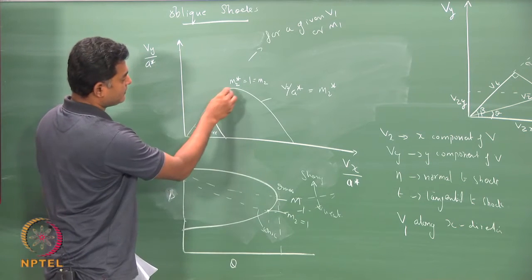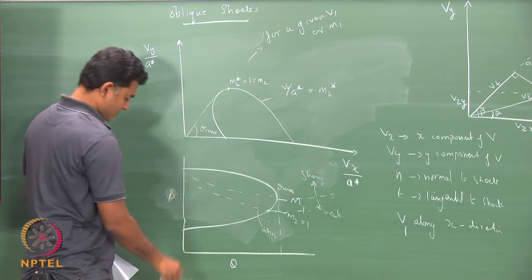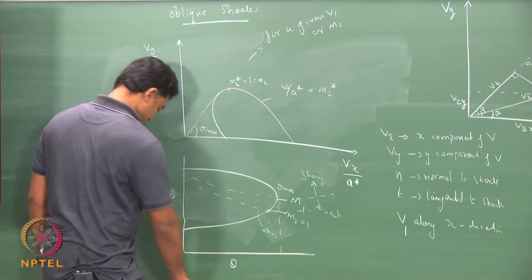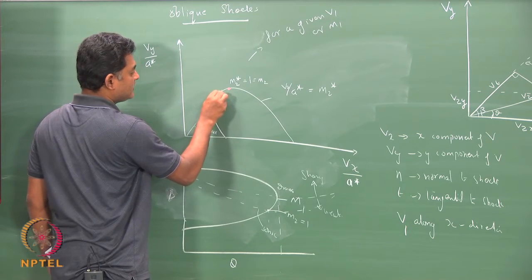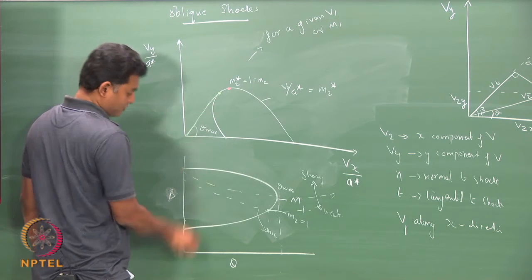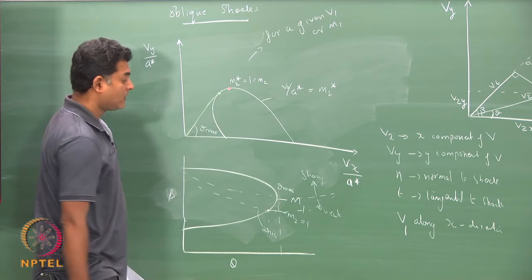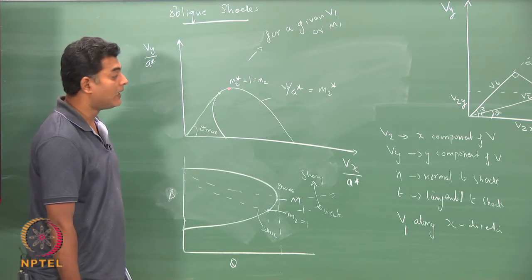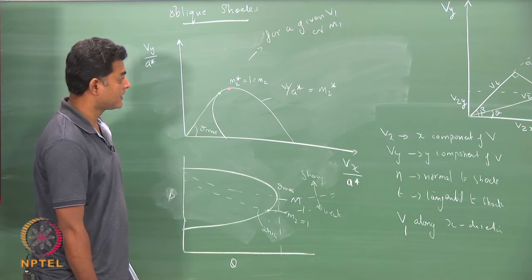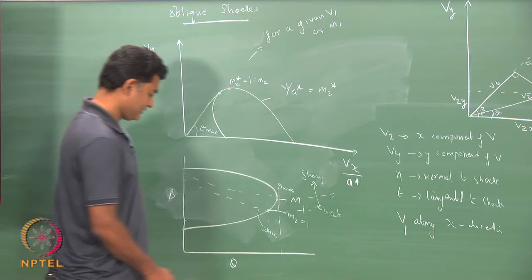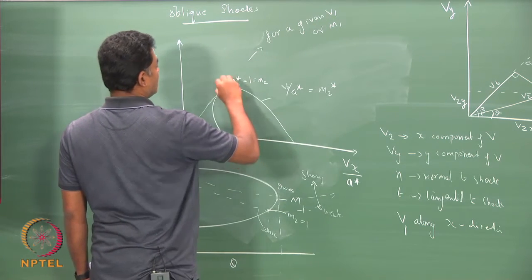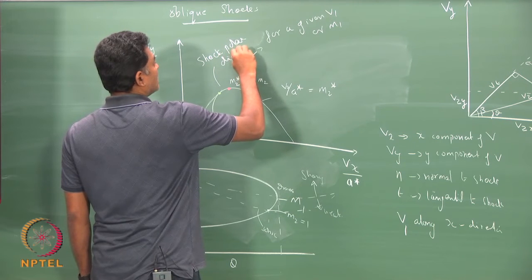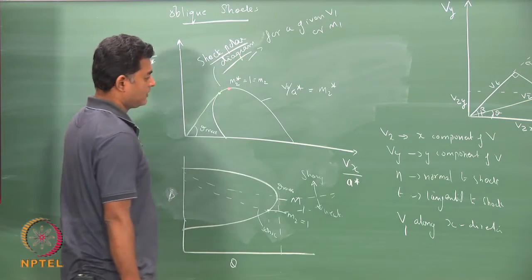Okay. So, this point is what I have written here as dot, and this is the theta max plot. So, I would put this red dot as my sonic line and this as the theta max. So, there are two different points as we have already seen in the theta beta M chart. And remember, this is for a given Mach number, given M1, okay. And this is the so called shock polar diagram, okay.